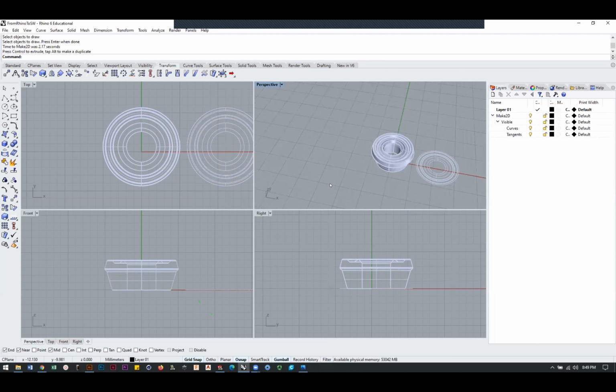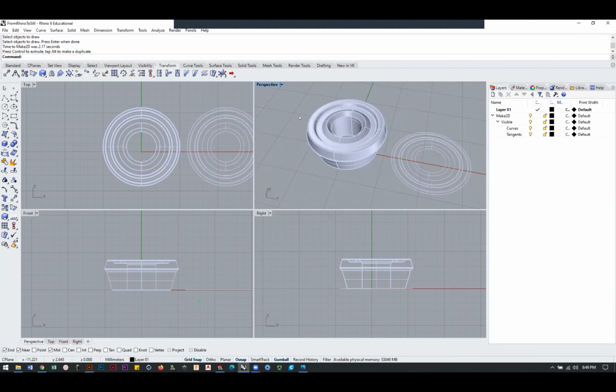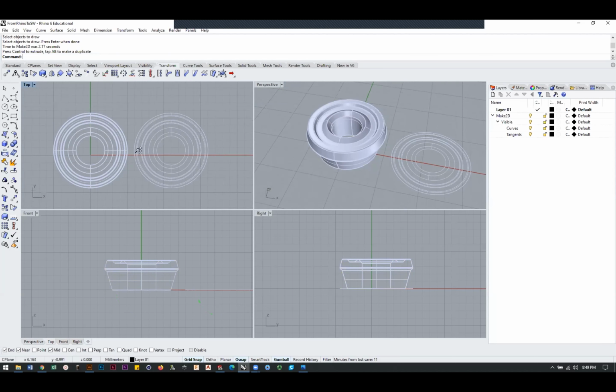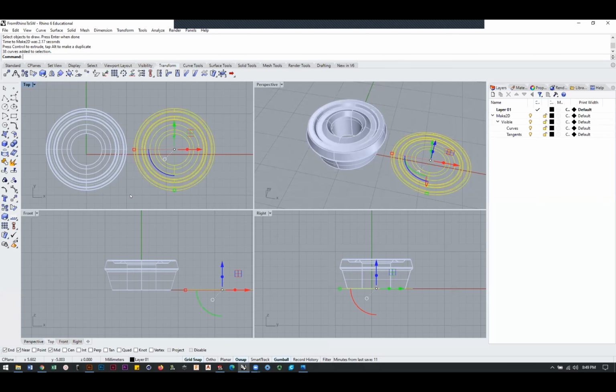If you haven't caught on yet, each of these viewports is also an area of construction. These are all construction planes. So by hitting the Make 2D construction plane option, you'll get a single flat 2D view from the top down of your design. Here's the bit of line work that was created, and here's the shape that created it.